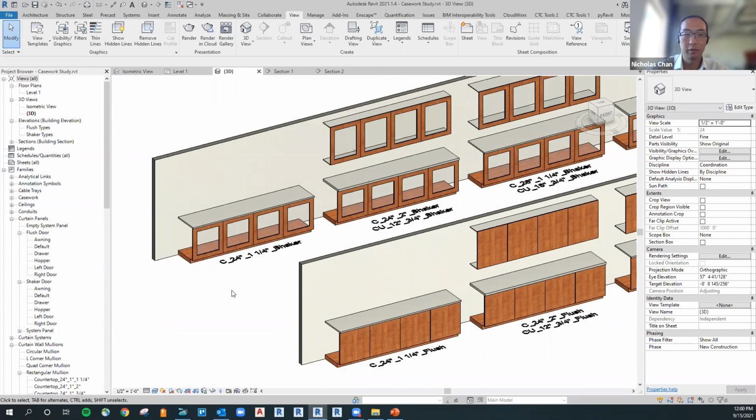I think there's a couple of questions just really quickly about tagging stuff. You can tag materials. Typically, we just tag materials and hardware and other objects, but that's completely possible with this, provided the materials are chosen and the tags are available. Plus, you can make a wall tag that appears to look like your casework tag. So it's simply going for that category. If you're using the tag category, it's just a wall tag.